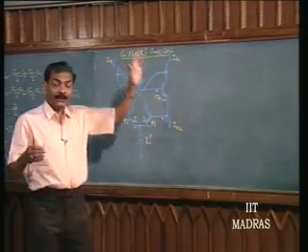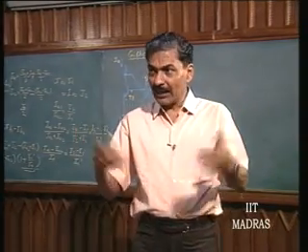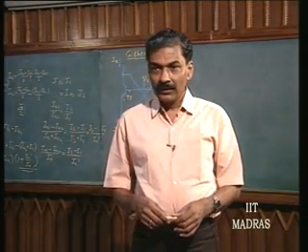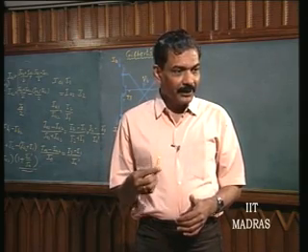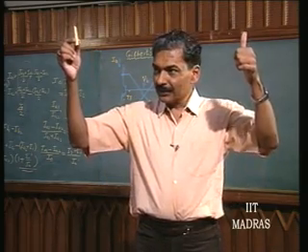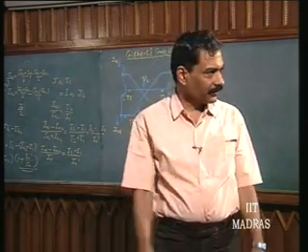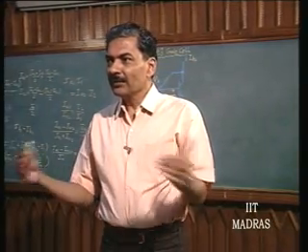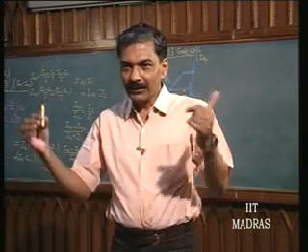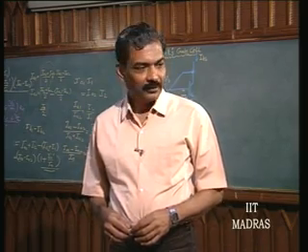You go on doing this and then where do you stop? Suppose you reach the current level that you desire, then you can now convert this into a voltage simply by putting two resistors to the final supply voltage and taking the differential output. So, converting a differential output current into voltage is simply by putting resistors. So, that is not a problem at all.